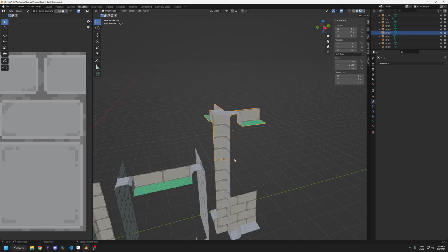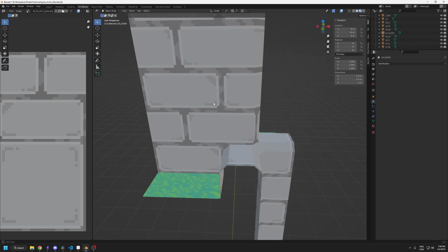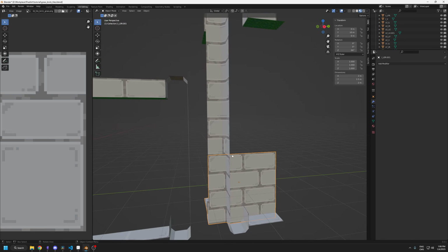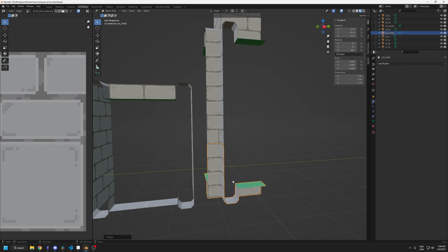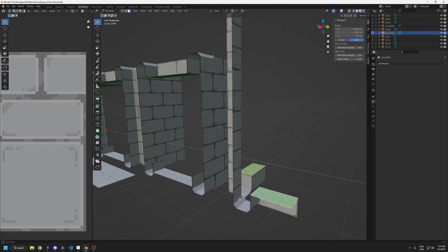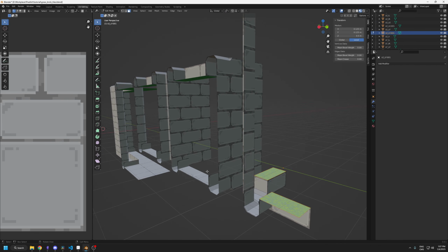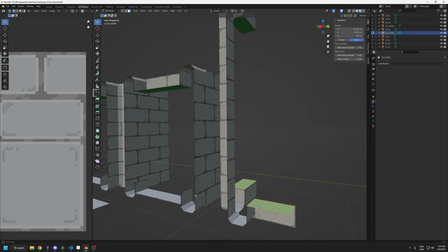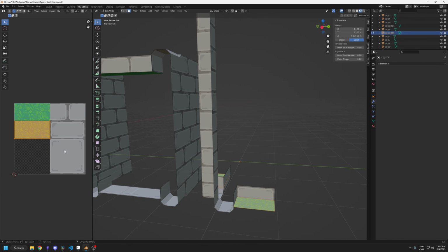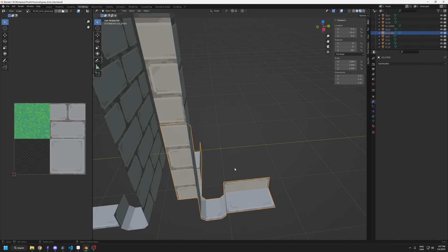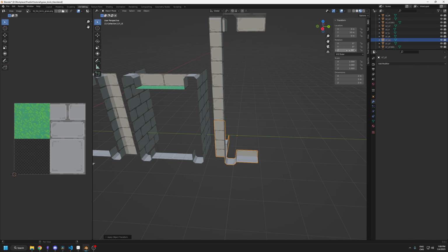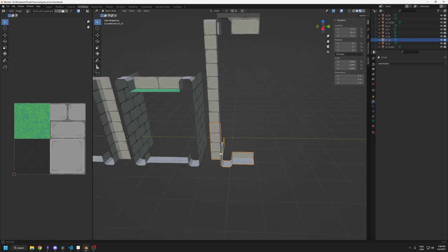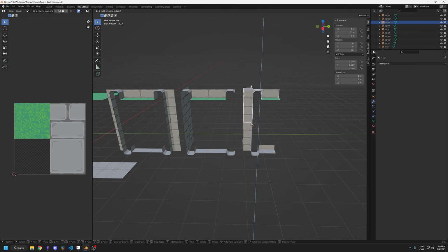And if I bring my outer corner on top, it should match. So yeah, perfect. For the bottom tile, I'll just duplicate the top one and scale it on the z-axis -1. It's going to be a bit faster. Then I'll select the grass faces. I'll press Y to disconnect them, and then I'll move on the z-axis and snap them to the vertices of the neighboring one, so the ceiling is at the same level. And I'll change the texture, and that's pretty good. So this one is LFLE, and then I need to apply the scale, and I'll apply the rotation also. All right, now I can delete the two corners I have here and move this one back down.